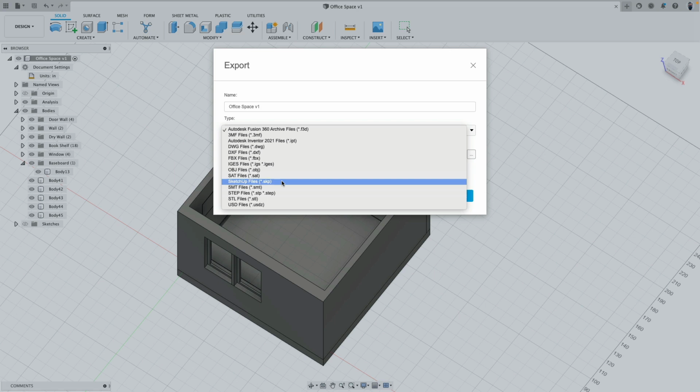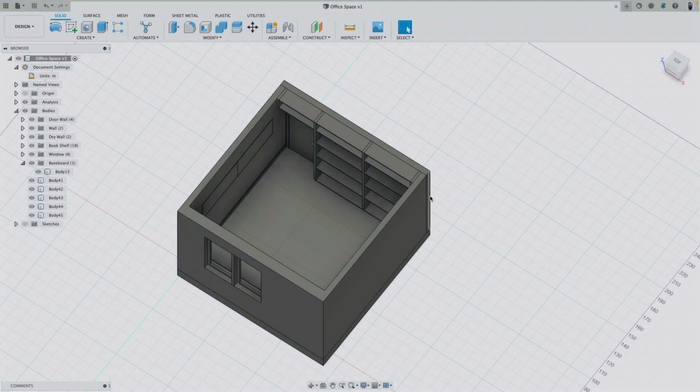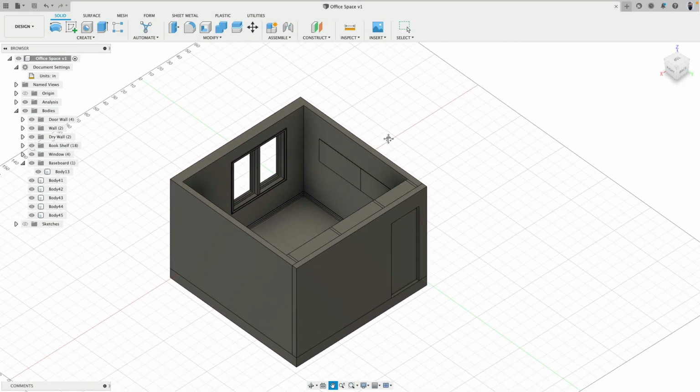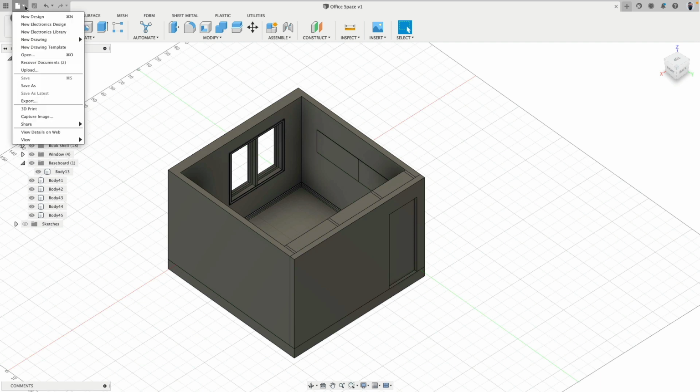For people who work with a render program like Blender, then we would just export this as OBJ. It would convert this CAD model into polygons and save it as the OBJ polygon format. So this is actually, I think, really good to know that you can use Fusion as a 3D modeler to create also spaces and assets for SketchUp.